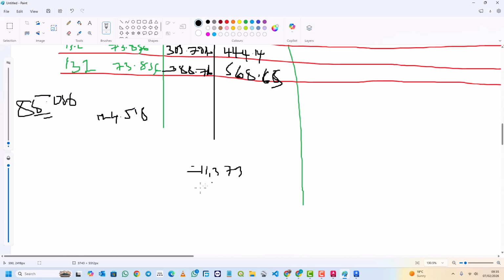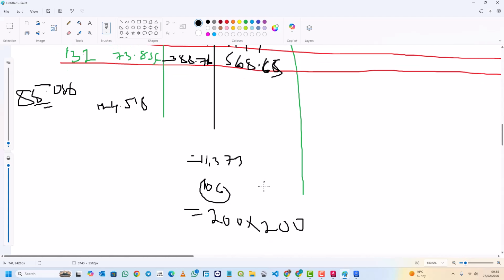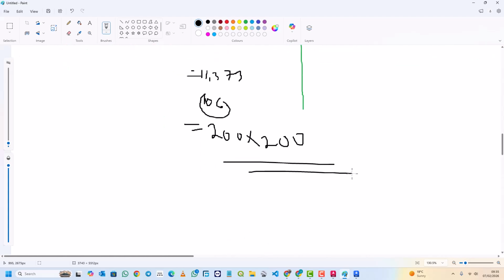So for preliminary design, you multiply by 1000 to convert to newtons, then divide by 50 to get the area of the bottom column that will be able to support all these loads. Then you'll get 106. So 106 is too small. You'll just assume a column of 200 by 200. Up to there, do you have any question?